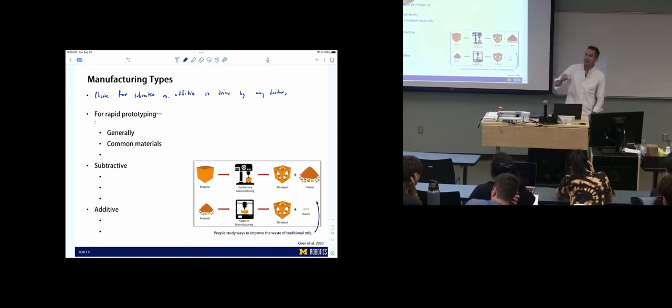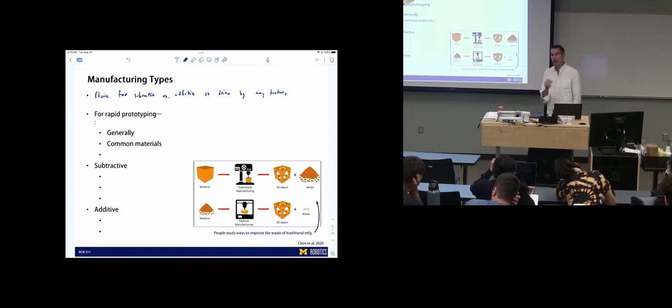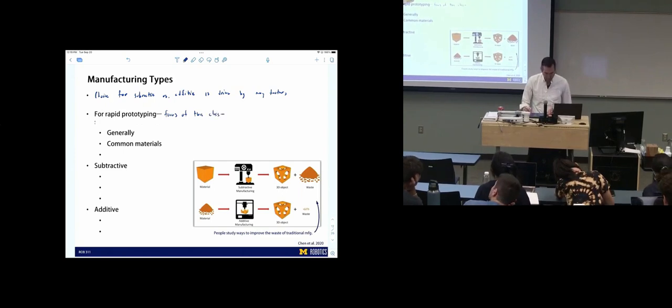A lot of it has to do with sizing, the size of your features, the size of your part, material properties, loading conditions. We'll step through these. For rapid prototyping, the focus of this class, we would want features that are probably on the order of tenths of millimeters to hundreds of millimeters. So if you're going to use rapid prototyping, or three different types of rapid prototyping techniques,